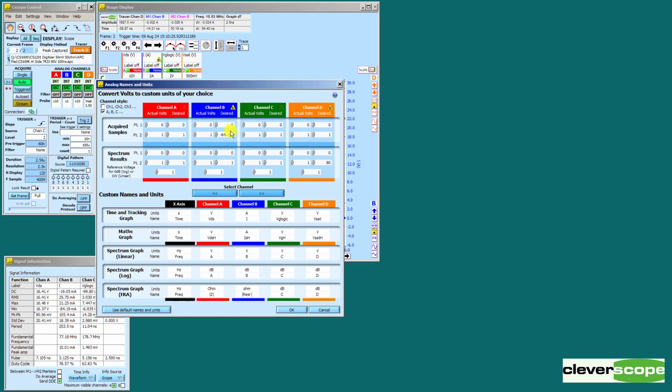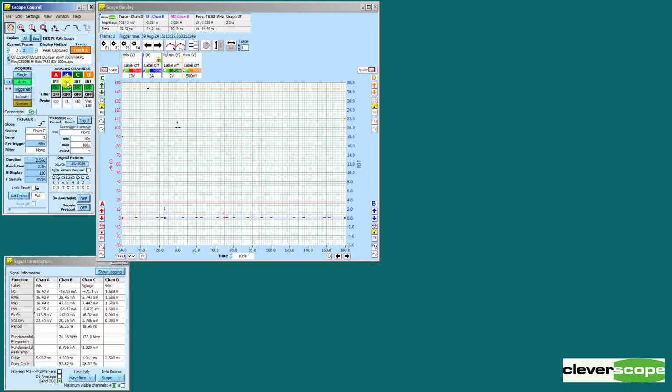It's quite simple to set values just by putting in pairs. This does gain and offset. I'll change the CS1201 internal channel to be remote. We're just waiting for the CS1201 to come online, and once it does, we're getting signals now.